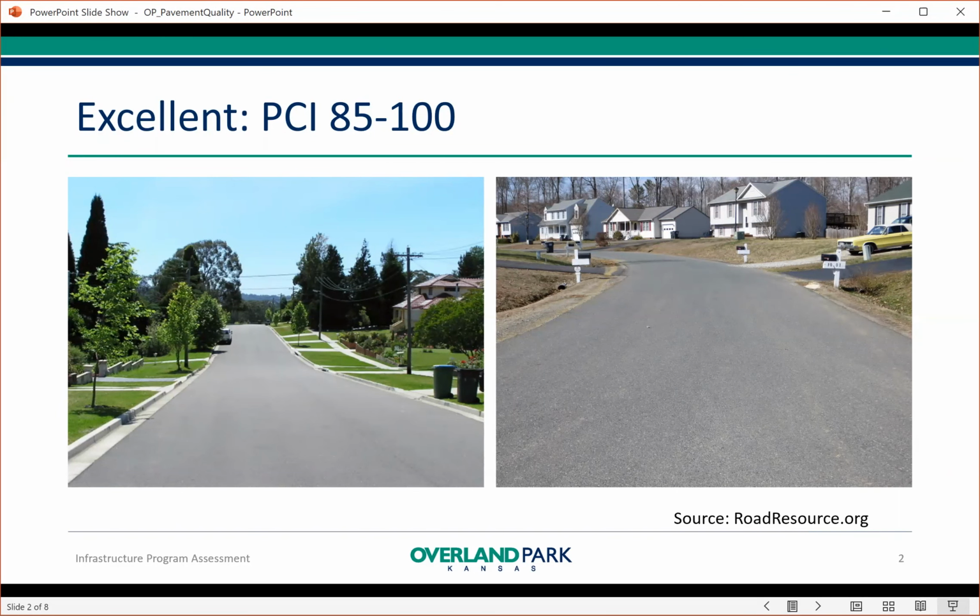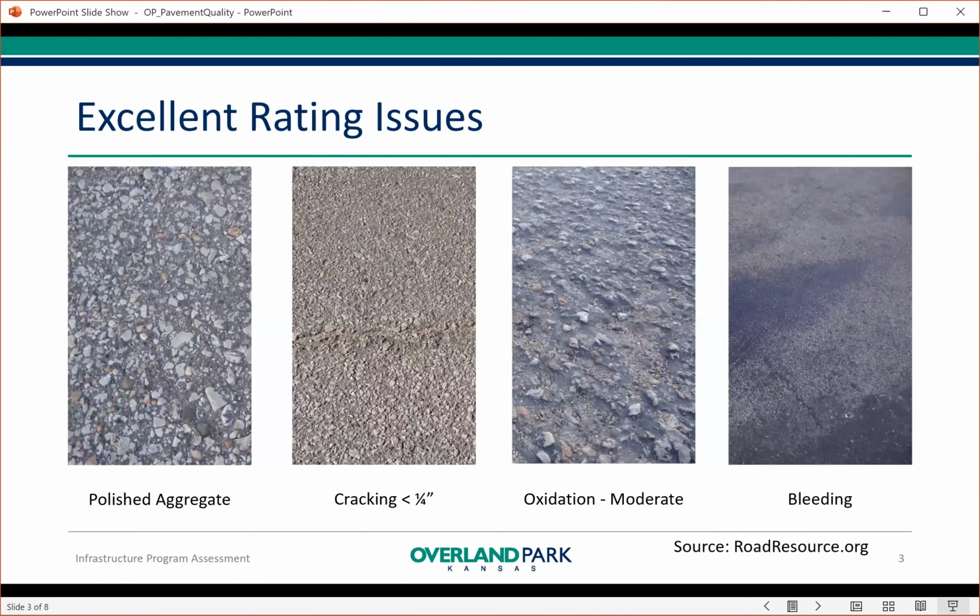While these streets appear ideal, upon closer examination, we begin to see the impacts from exposure to water, sun, air, and vehicular travel. Asphalt pavement is composed of aggregate and an asphalt binder. This binder is a semi-solid material that holds the rocks together. Think of it kind of like a very sticky and thick kid slime. Over time and exposure, the asphalt binder continues to harden and becomes brittle, losing contact with the aggregate that gives it strength.